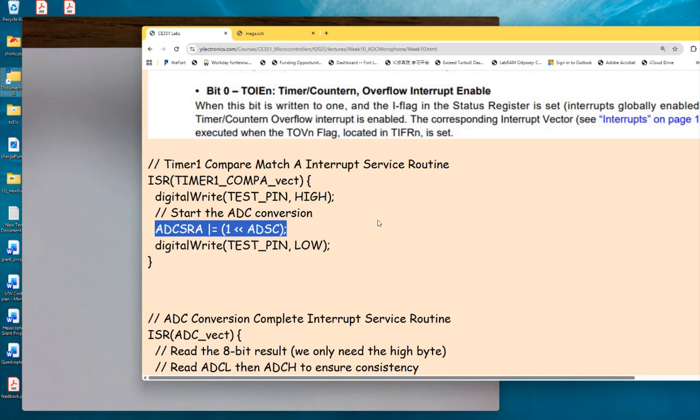Okay, so you can just do everything here, because the ADC also has an interrupt. Whenever the conversion is completed, it will interrupt. So you can look at the flag and decide if you want to do it here. However, keep in mind, you don't really want to put a while loop, a dead loop with a semicolon, inside the ISR. That's a good practice. Don't do it. What you want to do is use another ISR to detect the completion of the conversion interrupt of the ADC.